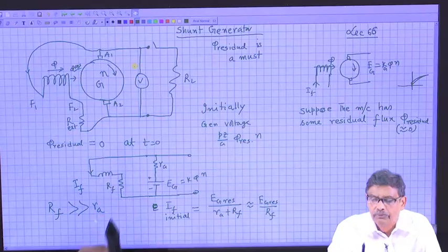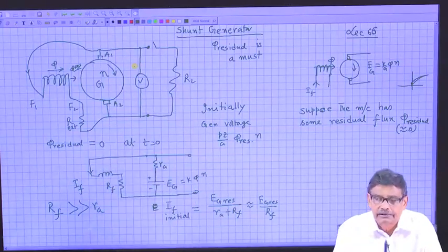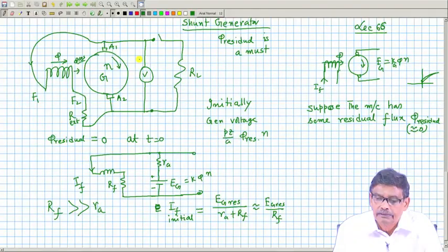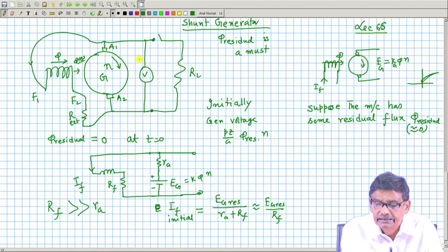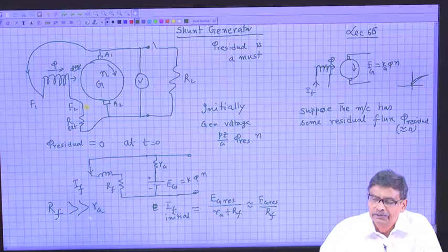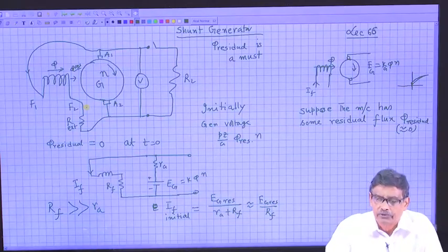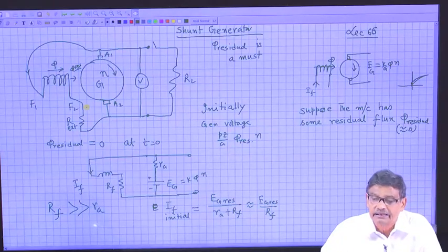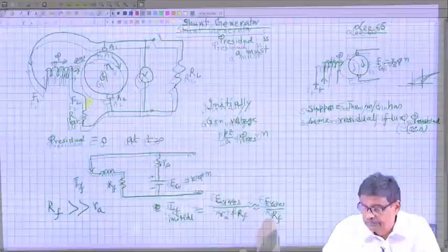This being known, now stop the generator. Then you interchange this polarity F1 and F2 parallel connected. I will connect this side now to A1, this side to A2. Then I would expect, because there will be residual field no doubt from left to right, but the polarity of the voltage will be such that it will decrease. Anyway, we will come to this much more.